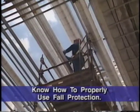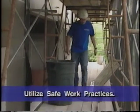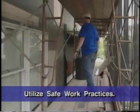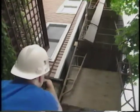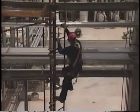Know how and when to properly use personal fall arrest systems. Inspect the equipment before each use. Utilize engineering controls, good housekeeping procedures, and safe work practices to eliminate the potential hazard of falling objects. By following the safe work practices and techniques presented in this program, you can ensure your safety against the potential hazards associated with scaffolds.